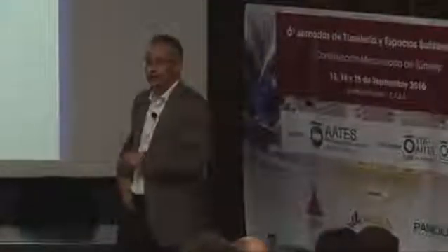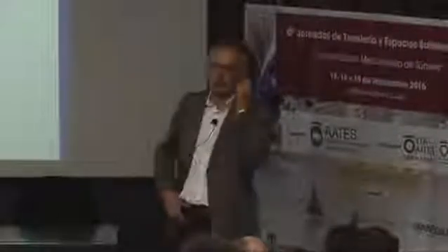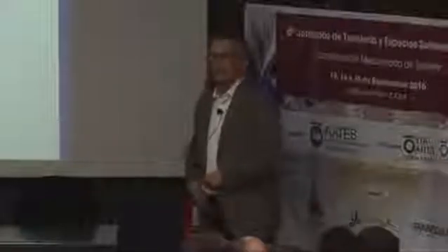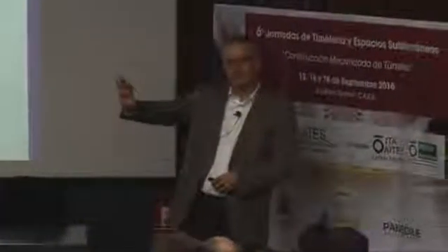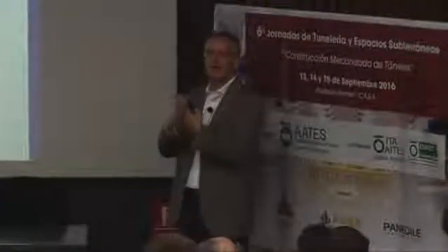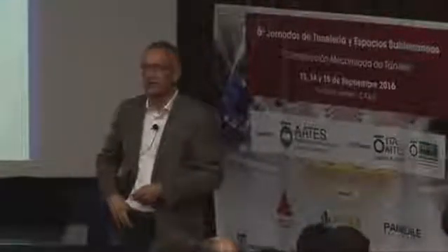You make a stop, you build the ring. Nothing happens, that's fine. You make a stop, you go home for the night. The bentonite suspension is still acting actively on your ground, on your tunnel face. And so over time, it is actually able to penetrate deeper into the tunnel face, indicated here with the blue section.